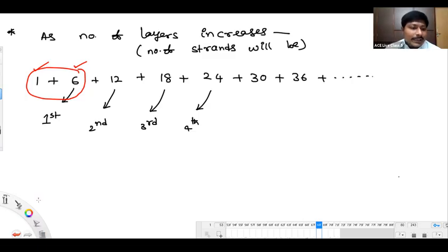30 aluminum. So let's say 12 aluminum I kept, but required aluminum is 30. So one more layer I should keep. So called this 18 also I will keep aluminum. Then what's the total aluminum now? That will be 12 plus 18, 30. That's sufficient. So internal 1 steel, next 6 steel, next 12 aluminum, next 18 aluminum. That makes the resultant conductor what we have given.